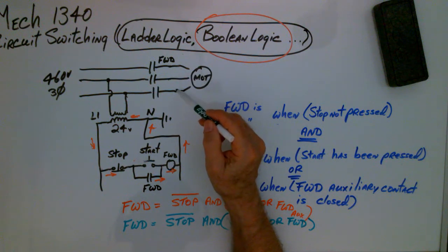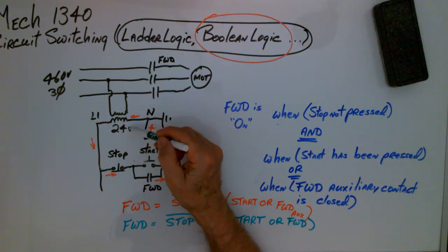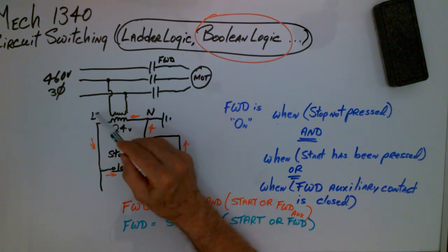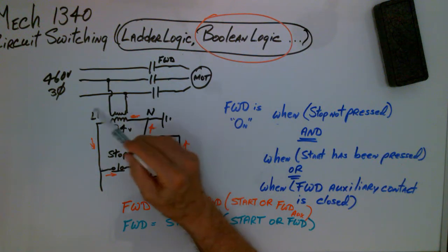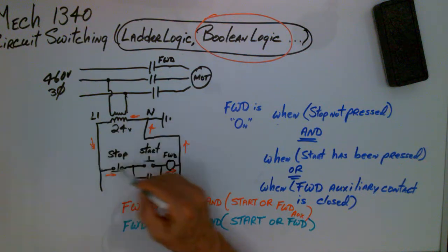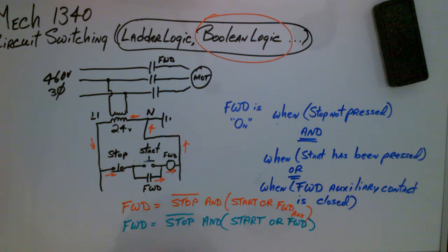Okay, so very simple motor circuit. It runs only in the forward direction. We have a control transformer. Okay, 24 volts in the secondary, that's safe voltage. And whenever you have a neutral, you should see a line 1 and a neutral marked in the secondary. And current will flow through these paths that I've shown you here. I must have erased one, right?